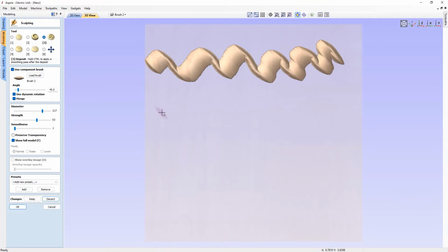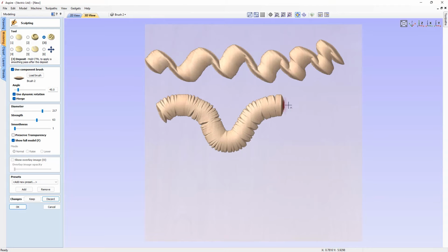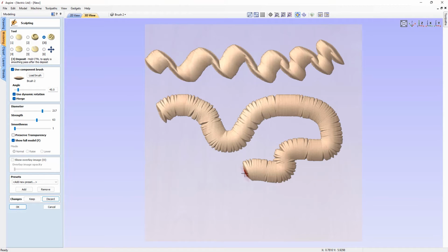And so now what we can do is when we move our brush, you can see I'm going down and up, and it's following the movements in line with how I'm actually moving the mouse there, and we've got quite a nice effect. However, it wasn't what I was quite expecting, and that's because the top of the brush is in the direction that will be forwards, and we can see that that's going to the left here. So what we need to do to adjust that is to actually alter the rotation of our brush.